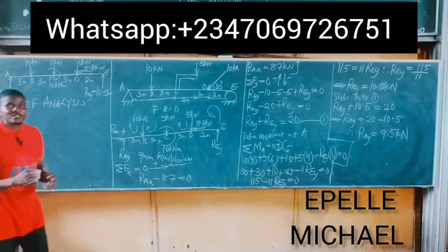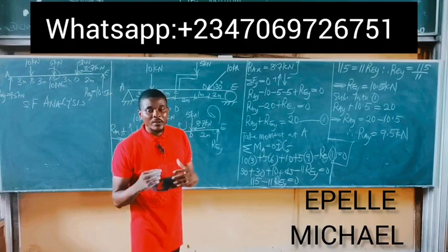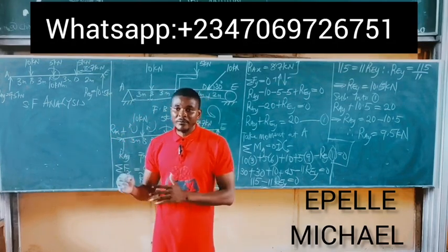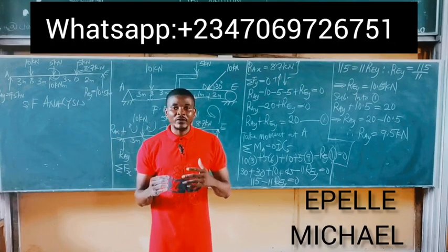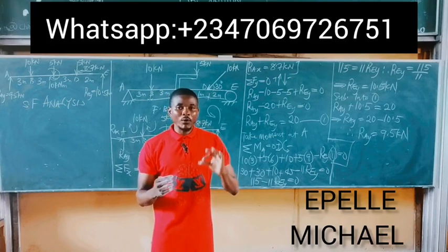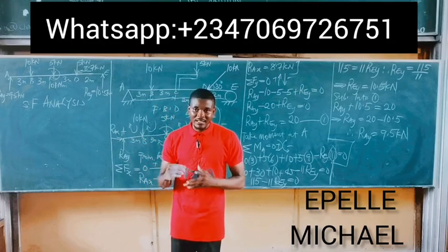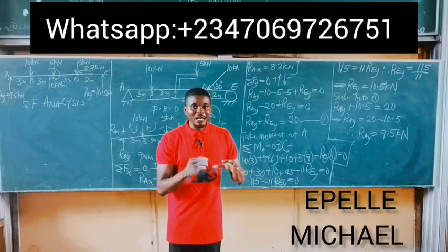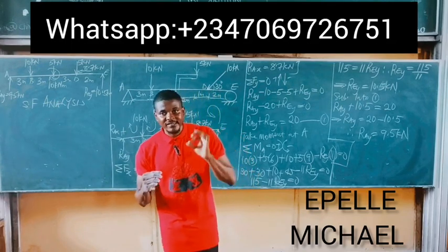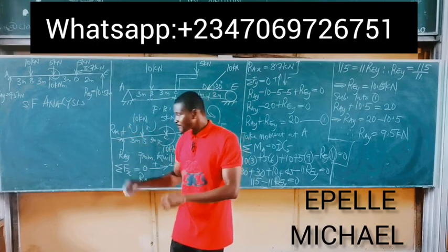Shear force simply means the summation of the entire force acting on the beam from the beginning of the beam at each point to the end of the beam, considering upward force to have a positive shear force and downward force to have a negative shear force. At the end of every shear force analysis, to show that the beam is in equilibrium, you must always obtain 0 as the answer. So let's treat that and see if we are going to have 0 in this case.